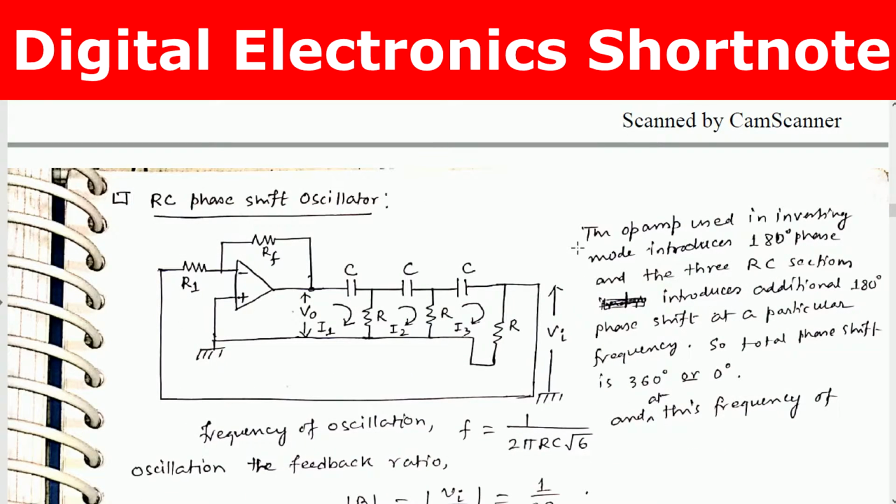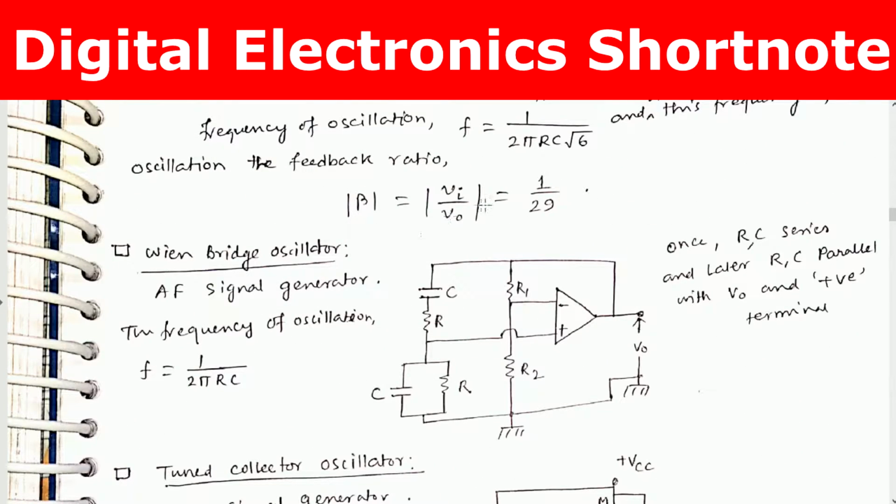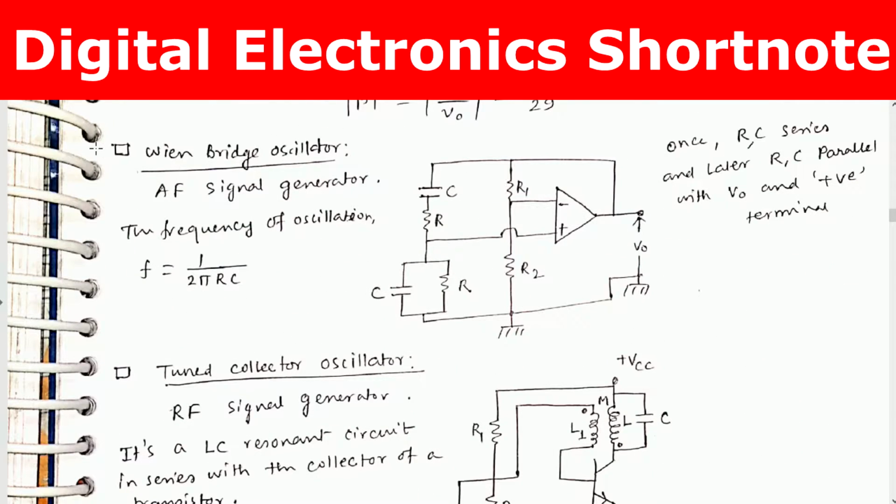RC phase shift oscillator. The op-amp used in inverting mode introduces 180-degree phase difference, and this is the inverting op-amp, and these 3 RC sections introduce an additional 180-degree phase shift at a particular frequency. So the total phase shift is 360 or 0 degrees. For this oscillator, the frequency of oscillation F equals 1 by 2 pi RC into root 6, and at this frequency of oscillation the feedback ratio beta equals Vi by V0 equals 1 by 29.